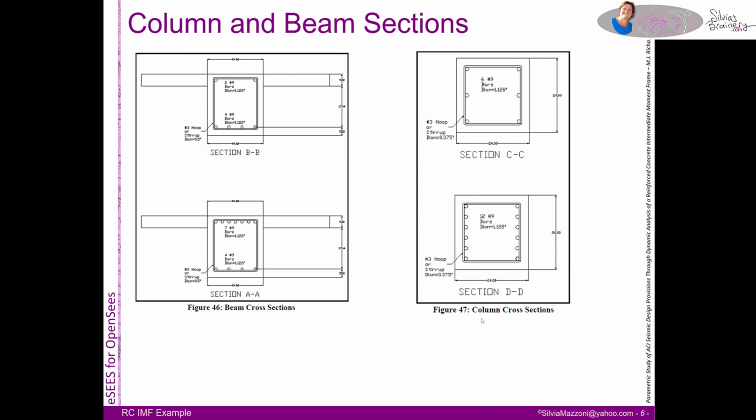Since there's this kind of information, it inspired me to build a fiber section. So actually I have 2 models going, one using hinge models and one using a fiber section. I could expand it and use a fiber section with a concentrated hinge element and show many different cases. But I really just wanted to compare the 2 here to show you the range of possibilities.